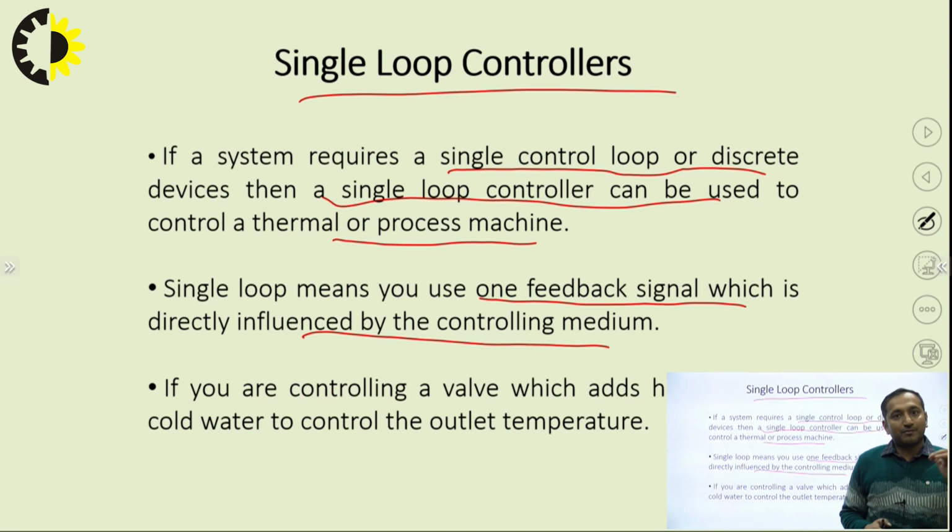It is done by the feedback mechanism. There is a temperature sensor there which automatically sends the temperature, to check whether it has met the set requirement of 25 degrees Celsius. If it is reached, then the loop is completed and we can say that our task is done. So if there is only one feedback loop applied, then we can say that it is a single loop controller.